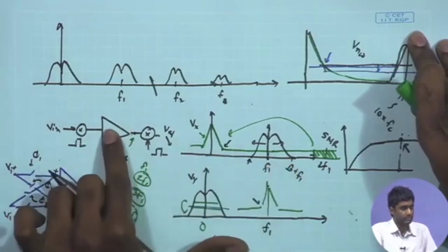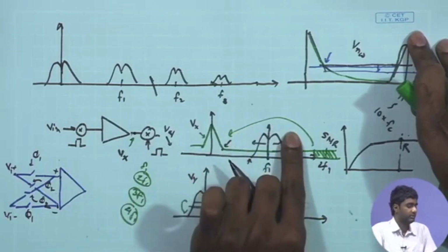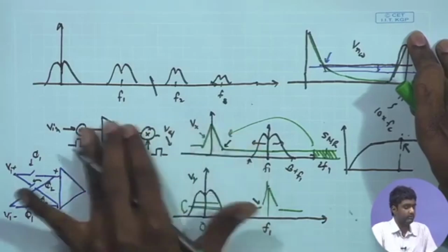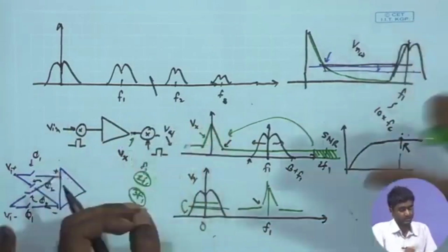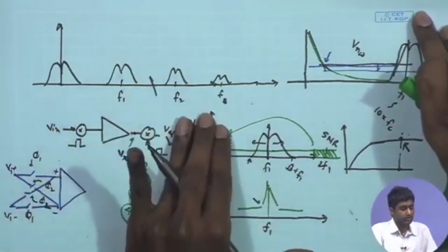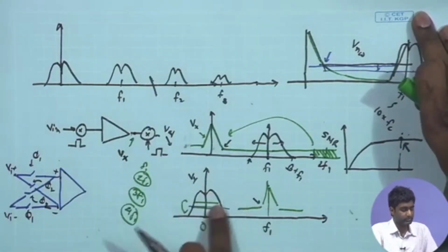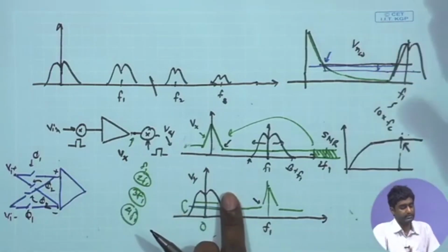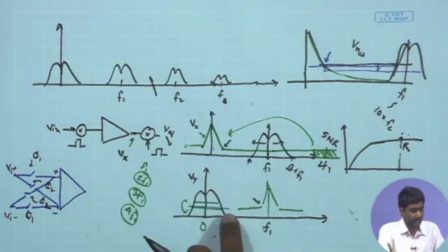The amplifier bandwidth is supposed to be high, but after that there is the low pass filter, the anti-aliasing filter that we have, or the subsequent amplifier stage. Even after that, as I said, you will need another amplifier stage which is probably going to be a variable gain amplifier whose gain needs to be controlled in an automated fashion. So, that itself will not require chopping and its bandwidth will be much lower. So, low pass filtering will be inbuilt in the circuit stages subsequent to this also, and beyond that you anyway have the low pass filter.